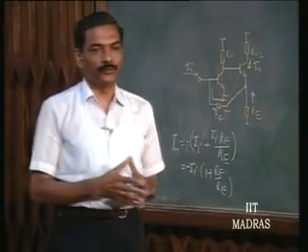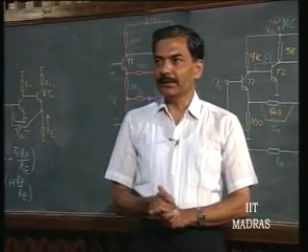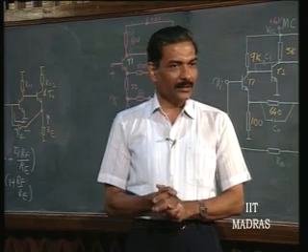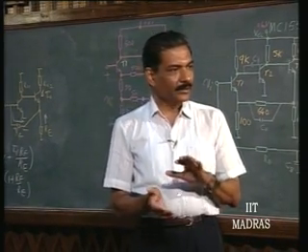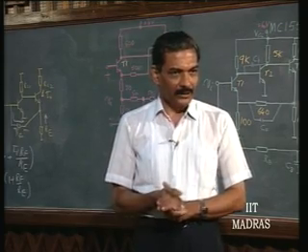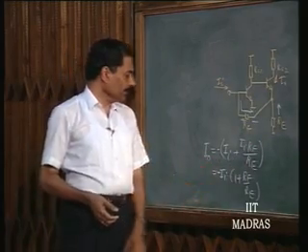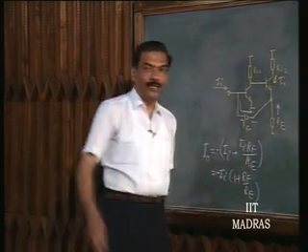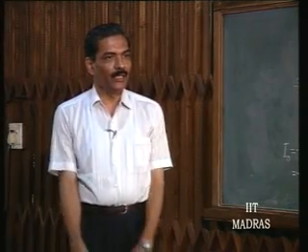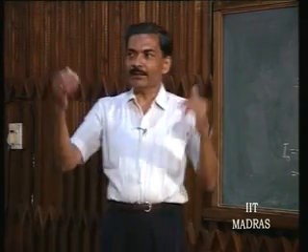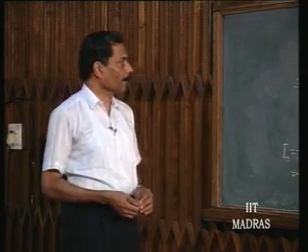So, you can see therefore that this is going to be the gain of the stage. It has an exactly identical method of analysis, except that the voltage and current change their role in this case. So, 1 plus RF over RE is the current gain in this case. Input impedance gets reduced considerably by the extent of the loop gain. Output impedance gets enhanced considerably by the extent of the loop gain, and the bandwidth improves by the loop gain.